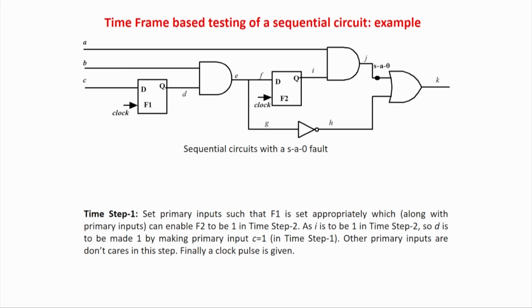So, test pattern generation time is highly optimized if you are using a scan chain, but test application time is not solved. If there is a scan chain whose length is say 10,000, that means, for example, if some of the flip flops are at a depth of level 1000, the scan chain length also will be 1000, because this last flip flop depends on the path from the primary input. If you take a path to the primary inputs, there will be 9999 flip flops in the path. So if you make a scan chain, the scan chain length also will be of the order of 10,000, and you will require 10,000 clock pulses to feed it.